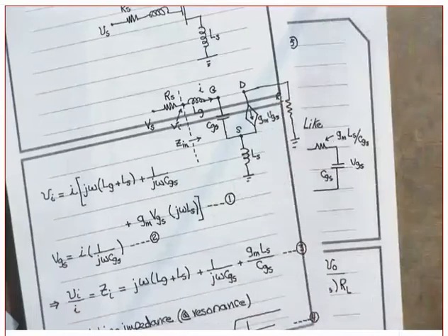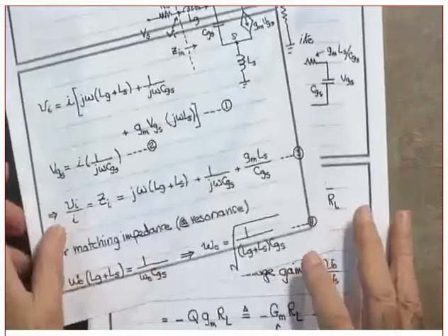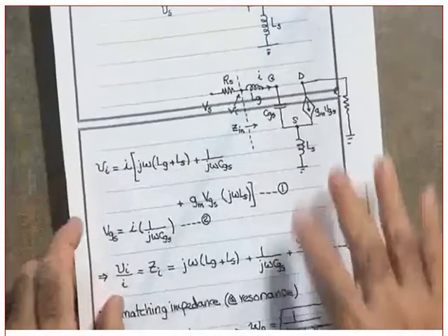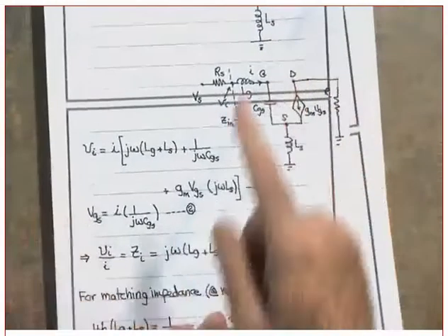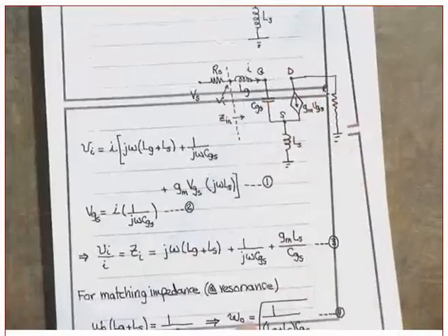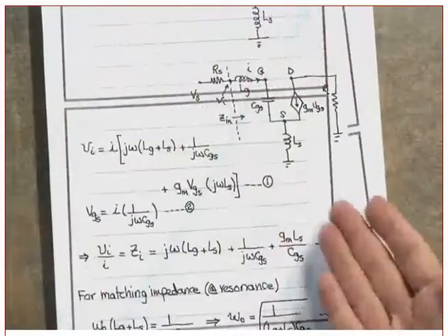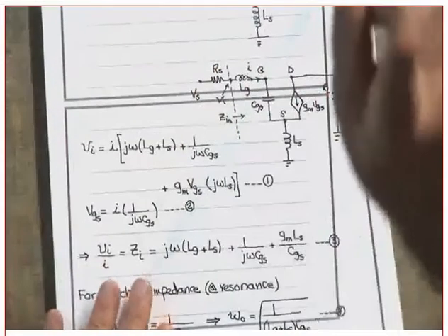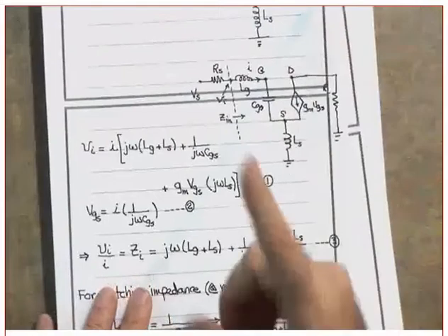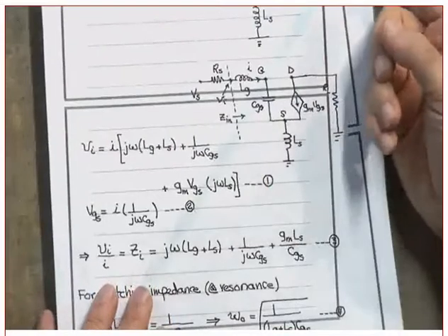Okay, what is your question? Yeah, I mean, this circuit will only be working on the resonance frequency. Which means what, by the way? What does that tell you? What kind of an LNA is this? Is it a wide band or is it a narrow band? That's a narrow band. Why? Because this only occurs at one frequency. Are you following me or not?